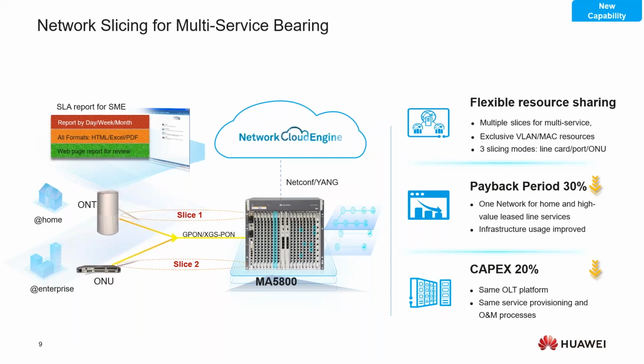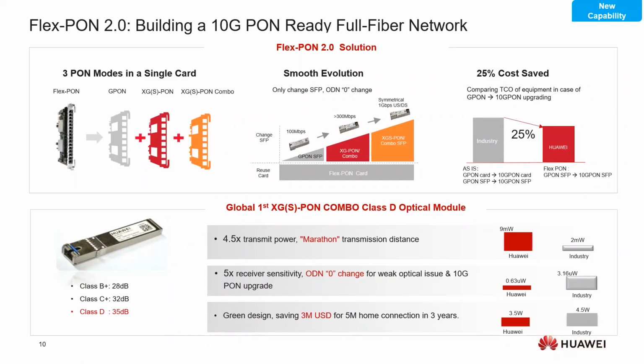So that is one thing, on the network architecture to support multiple services. And the second topic will be the smooth migration from the existing generation GPON into 10G PON, XG or XGS PON in future. It is also a highly concerned topic in our poll. The consideration here is to introduce flexibility in this migration, and to avoid difficulties in network construction on the choice of each of them. So from the technical perspective, the OLT platform or even the LAN cards should be designed as a single one, supporting multiple generations or multiple options of the future PON or 10G PON technologies.